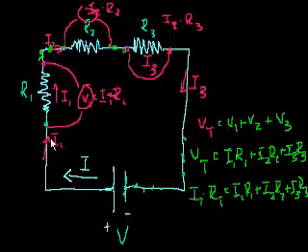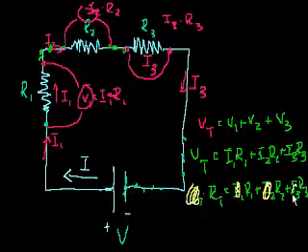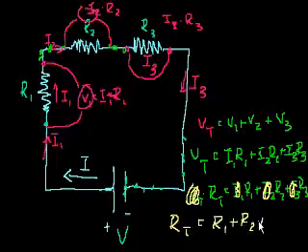Hopefully you can take it as just conceptually it makes sense to you that the current through the entire circuit will be the same. So all of these I's are the same, so we can just cancel them out. Divide both sides by that I, we assume it's non-zero. And then we have that the total resistance of the circuit is equal to R1 plus R2 plus R3. So when you have resistors in series like this, their combined resistance is just equal to their sum. And that was just a very long-winded way of explaining something very simple.